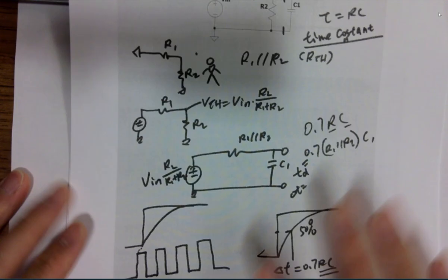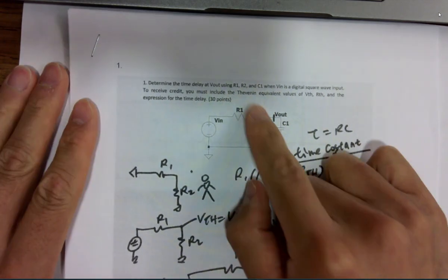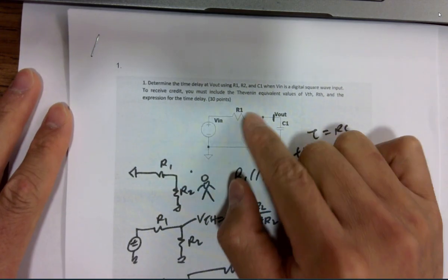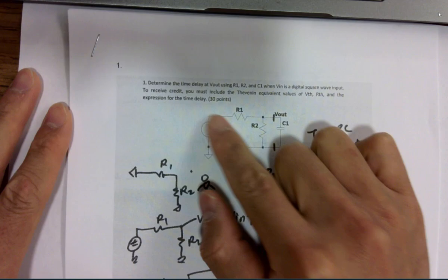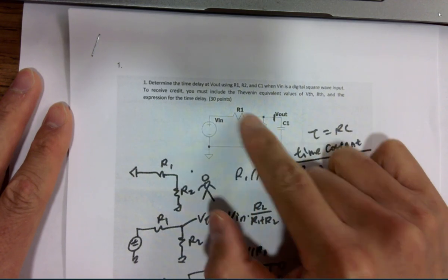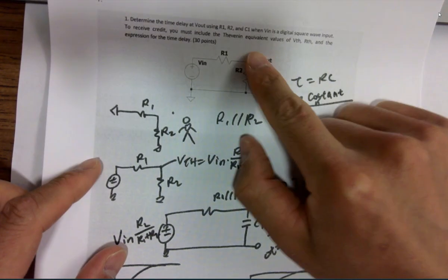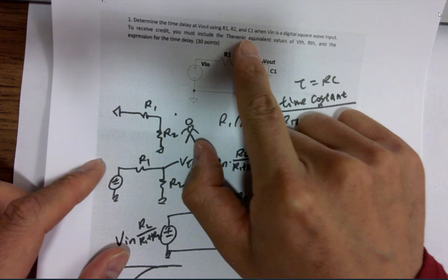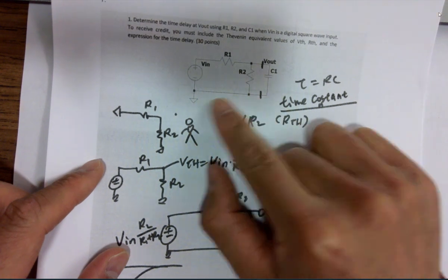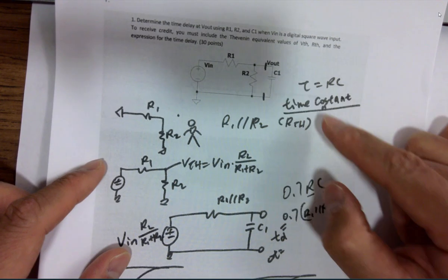But you know that for this one, if I'm asking you, the circuit over here could have more resistors in the network, so you should still be able to simplify it. The 7 is equivalent, and then to find out the time delay, right? The time delay here is just simply our RC circuit. So convert whatever here into its VTH and RTH, and then it becomes a very simple RC circuit like this.